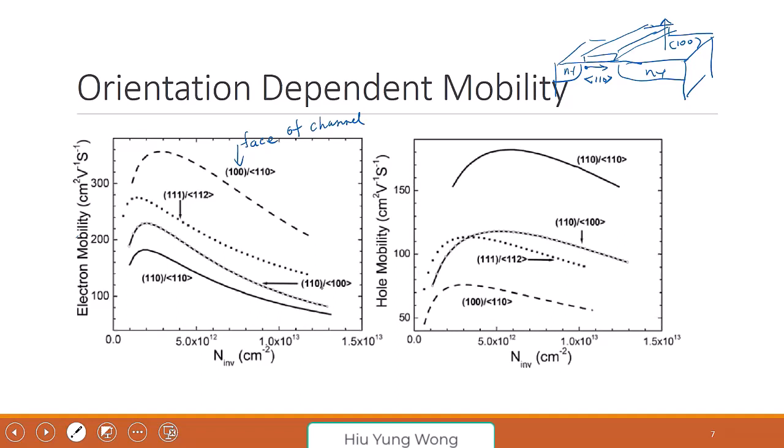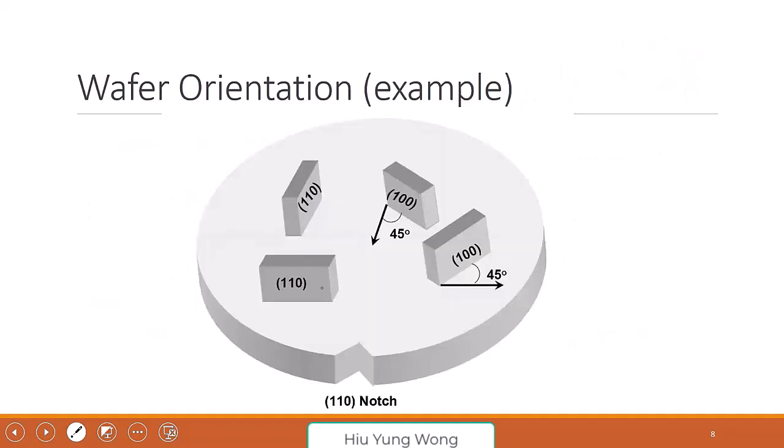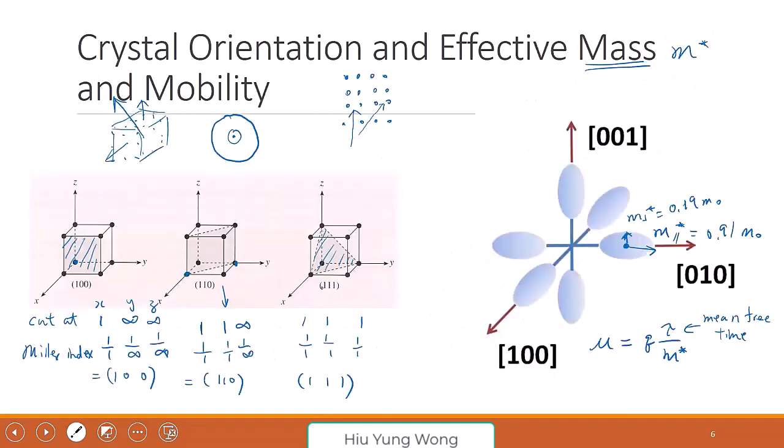Yes. Okay, good. Is the orientation of the silicon usually designed or fixed? Yeah. Usually when they make the silicon wafer, they cut in the 100, 110, and 111 directions. They try not to cut in some arbitrary orientation because the demand for these is the highest.